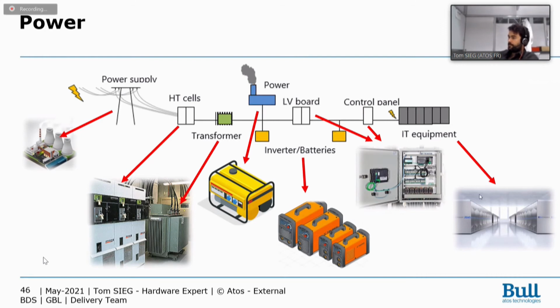And at the end, your HPC cluster. Into your HPC cluster, your electricity is maintained, of course, by PDUs, and you will also be able to put a battery and inverter inside your data center room. But when you have a data center, it's more efficient to have an external battery and inverter before the last control panel or before the LV boards.